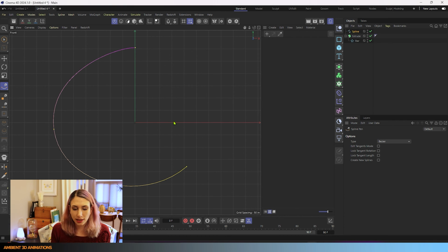It can affect how Cinema 4D calculates your textures when rendering. So you need to let it know what's the inside of your model and what's the outside of your model, and it does that with normals. And I have a whole other episode just on how to fix the normals within your models. But for right now, we're going to go through this just for the extrude tool. If you want to learn more about normals, I'll leave a link to that episode below.